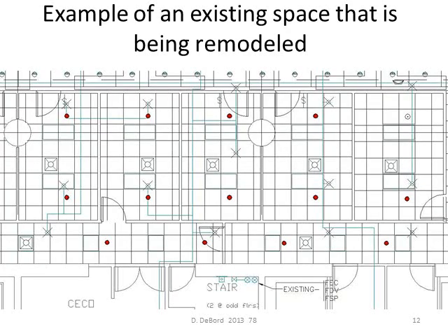It's an example of an existing space that's being remodeled. We see the existing sprinklers with a circle. Piping is green again. Wherever we relocated the sprinkler, we showed a solid dot, and here it's colored in red. And we put an X through where the sprinkler was.